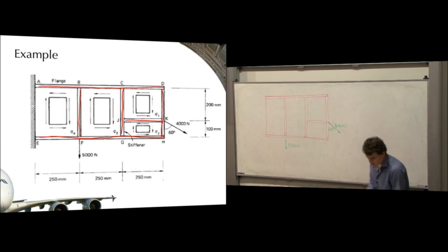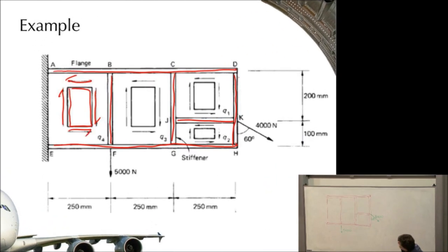Now the way to read these little pictures of shear flow here, they have a little arrowhead on all of them. What that arrowhead means is, if we make a slice and we need the shear flow on the left-hand side of the slice, the arrowhead tells us the direction it's going to be acting. So we've made a slice through our panel just inside the wall.